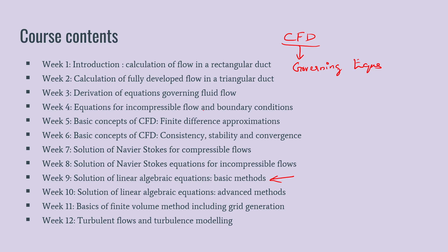When we have a problem in our hand, to do the CFD methodology, what we would be following is to apply the governing equations that match the physics of the problem. Then this governing equation will be reduced to a set of algebraic equations.